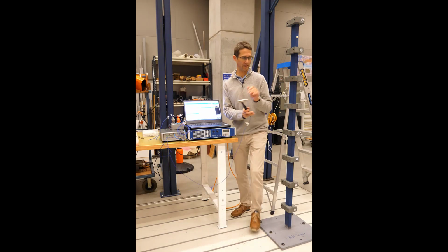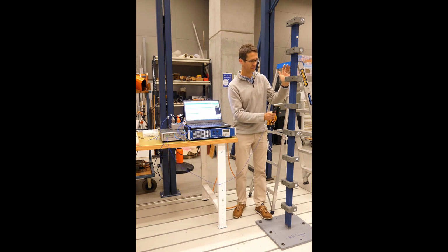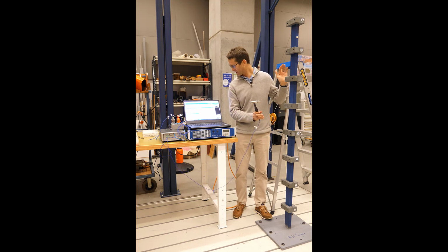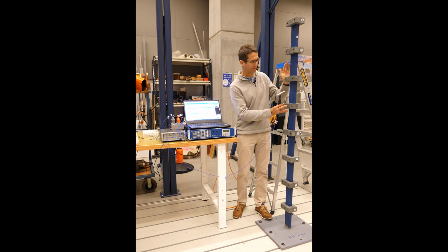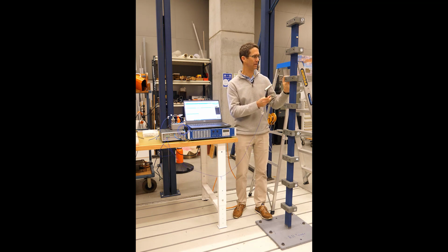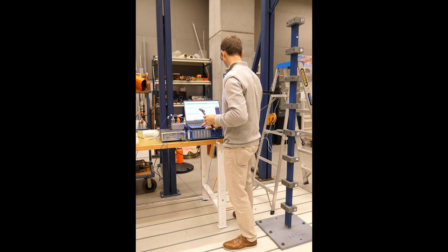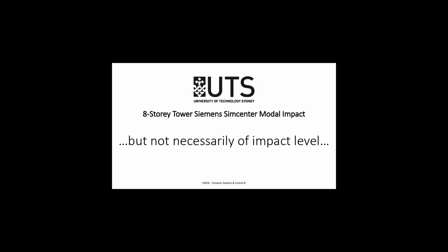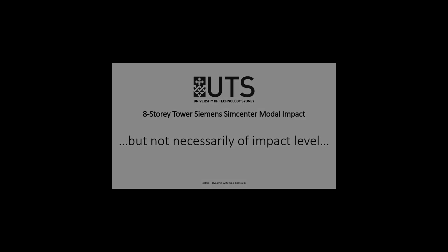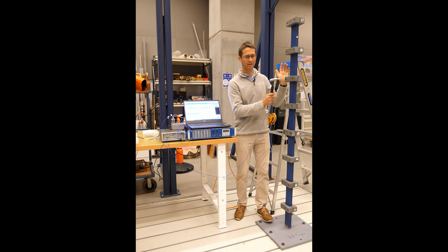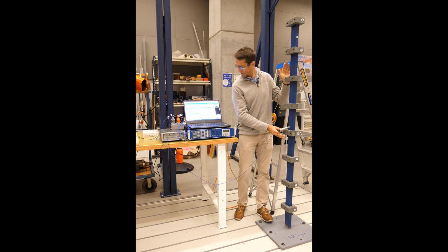Now at level 5, and I'm just doing 3 averages, which is pretty much the bare minimum. I don't see much improvement after 3 averages. I might want to convince myself that I don't get any better FRFs for doing 5 averages. As you can see, with a bit of experience, it's quite a quick experimental measurement campaign to collect all of these data.